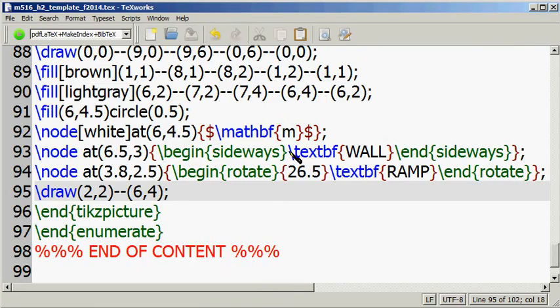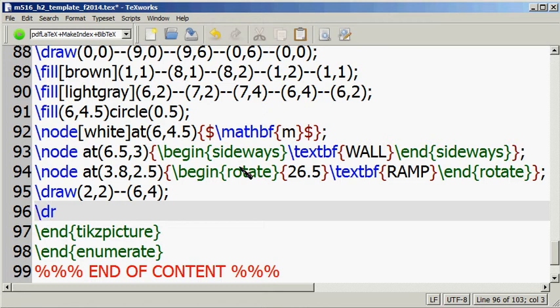In order to draw arcs, we say draw, and then you have to specify the location where the arc is going to start. So that's 3 comma 1, and the arc. Then this is a tricky one. So this is a starting angle. It's going to start from angle 0 to about 26.5. So you put the 26.5. And then the radius is going to be 1, right? Then you see that this is going to look like this.